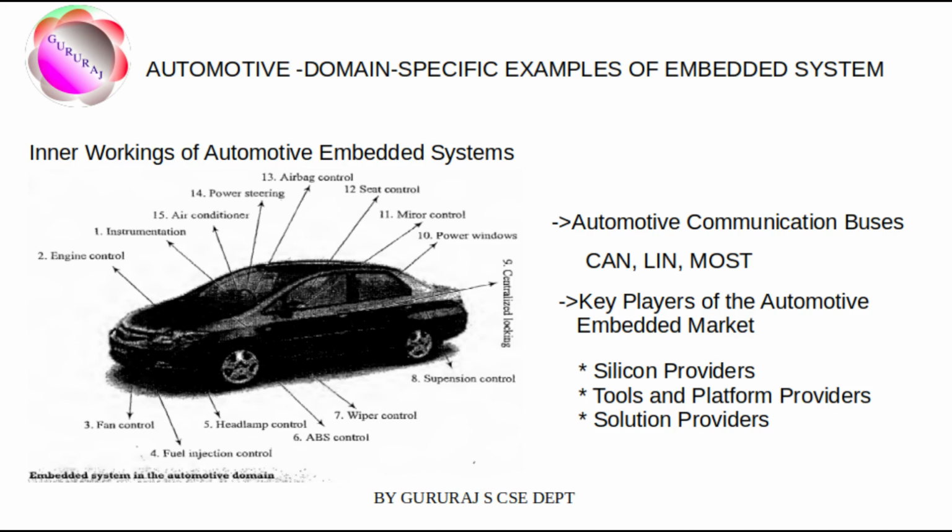Next is the Media Oriented System Transport bus. In short, it is called the MOST bus. The Media Oriented System Transport is targeted for automotive audio video equipment interfacing, used primarily in European cars. The MOST bus is a multimedia fiber optic point-to-point network implemented in a star, ring or daisy chain topology over optical fiber cable.